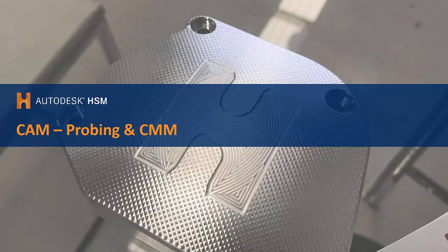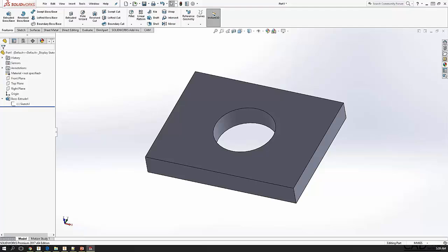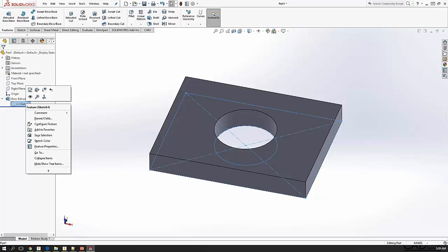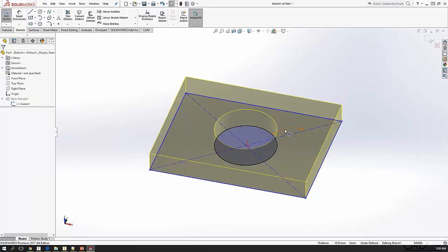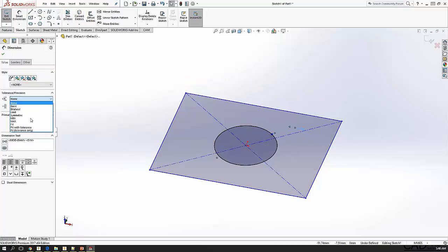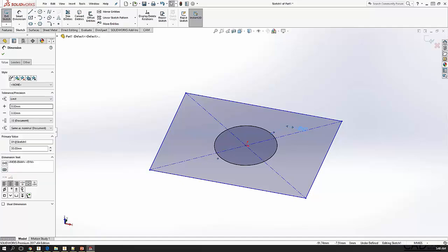This bit was, can you see my screen now, guys? Now we can. Yep. All right. This bit was a little bit unplanned, but I just wanted to point out, and I'm actually quite keen to find out whether any of you guys can tell us whether this is possible or not. I couldn't see whether it is, but in SolidWorks, when you edit the sketch and highlight one of the dimensions here, you've got the ability to set the tolerance and precision for that sketch dimension in a very similar way to what Gavin just showed inside Inventor. But the key step I'm missing here is how to get it to actually apply to the model.